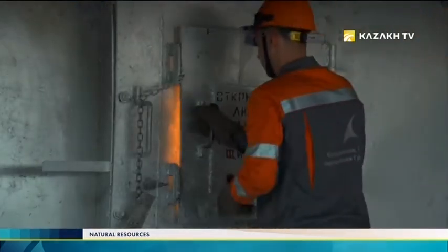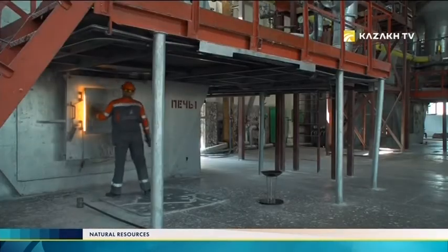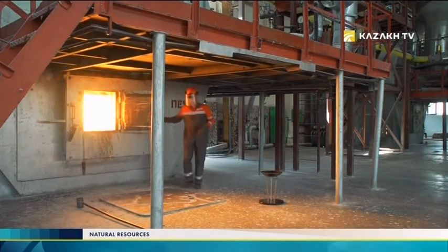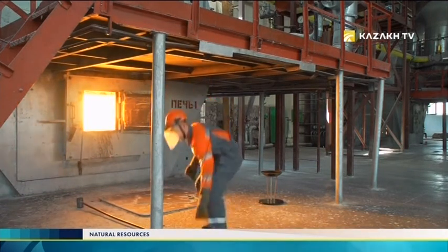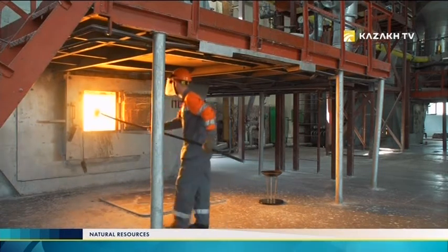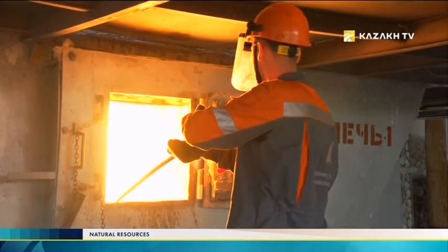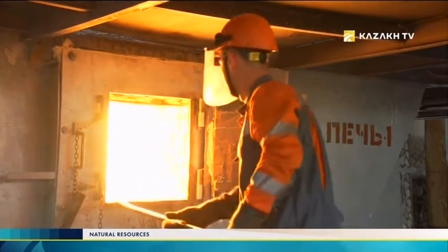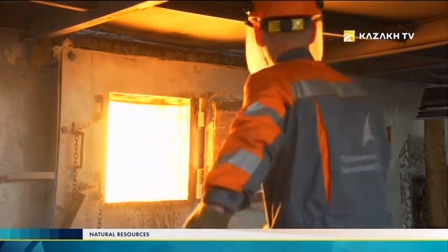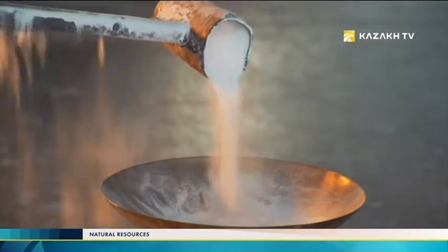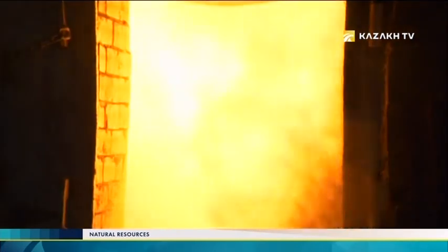The whole process takes place in these furnaces. They are divided into 4 sections. The first section is drying section, where water is evaporated out of aluminum hydroxide, and the temperature of material does not exceed 200 degrees. Then, in the calcination section, chemically bonded water is removed, so that hydroxide passes into waterless state. Here the material temperature is 950 Celsius degrees.